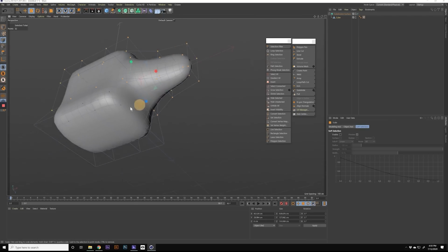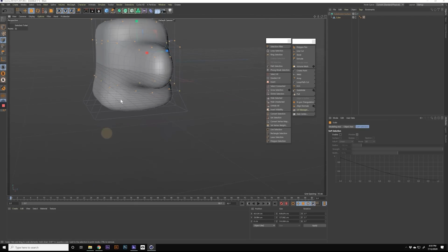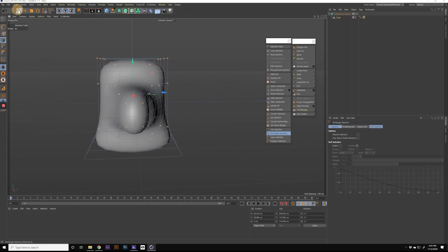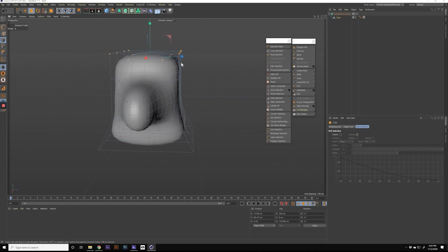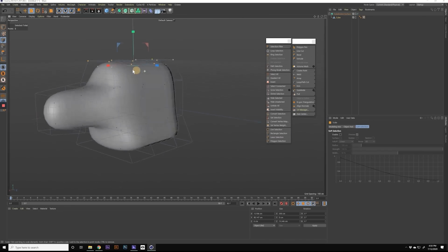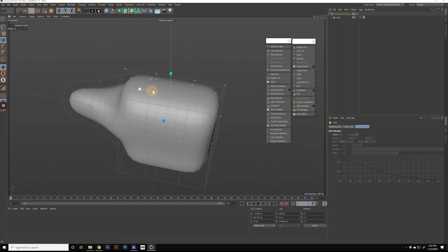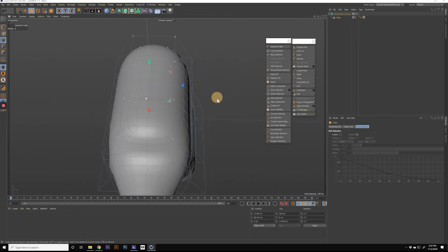So the base is staying this cube, and then we're just gonna kind of make things a little skinnier as we go up. So back to the rectangle tool, let's select just these top polygons as well. Press T and make those a little bit skinnier as well. Just kind of folding our hand to the top where these fingers are gonna come out of.